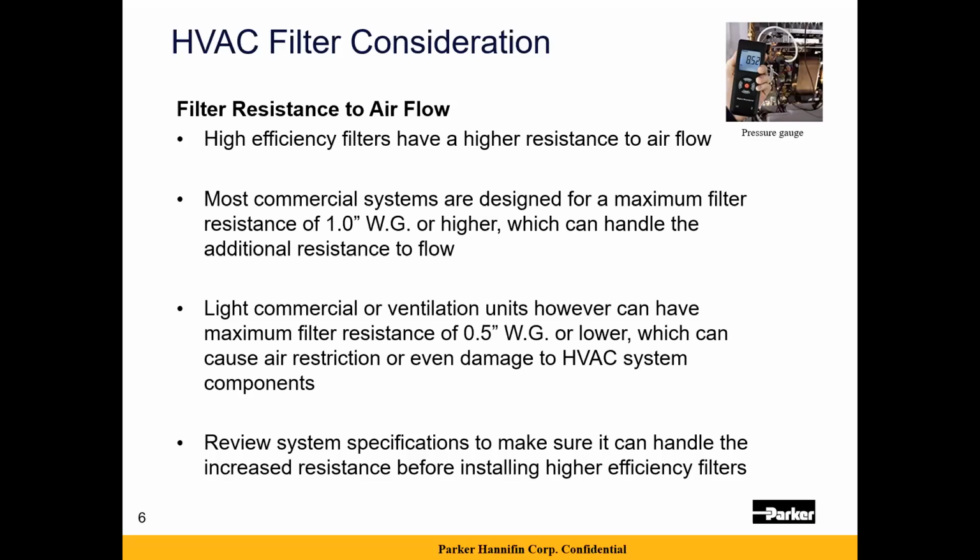So when a customer is wanting to improve filter efficiency, the first thing that needs to be done is to review their system specifications, what kind of filters, what kind of airflow rates it can handle before making a change to a higher efficiency product.